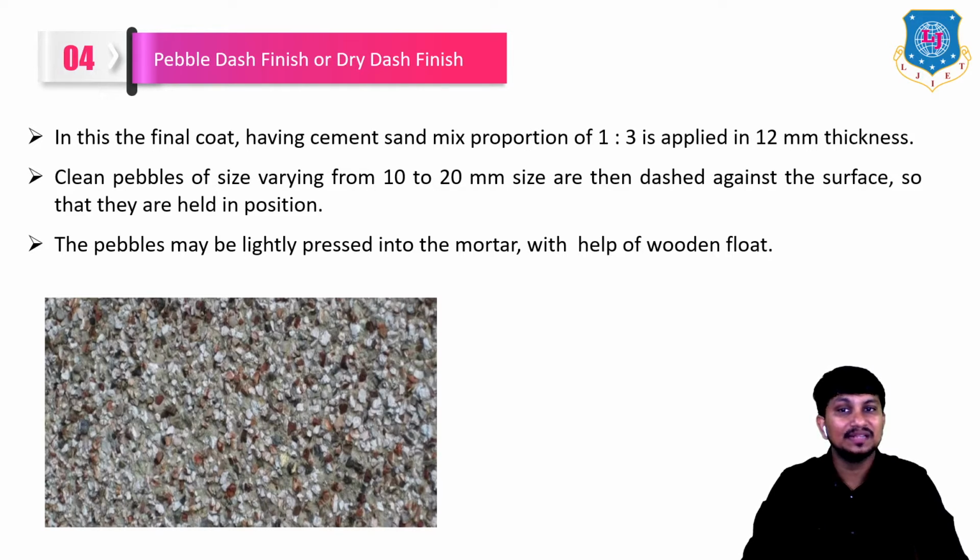These pebbles may be lightly pressed into the mortar with the help of a wooden float. Okay, so this is how you can make this type of pebble dash finish, or you can say dry dash finish.